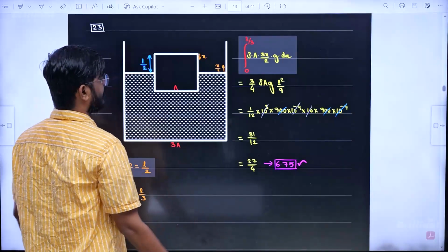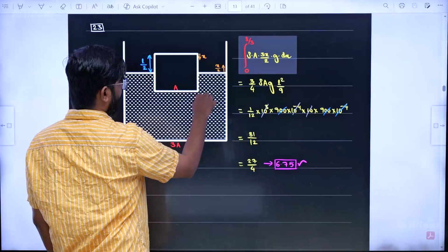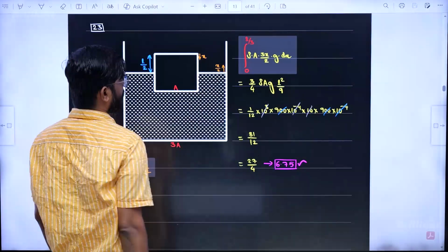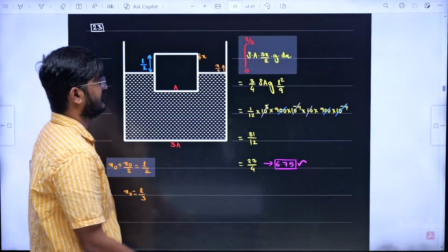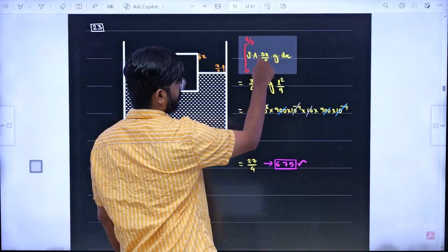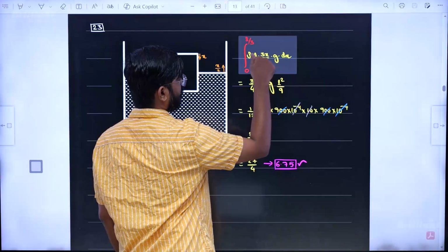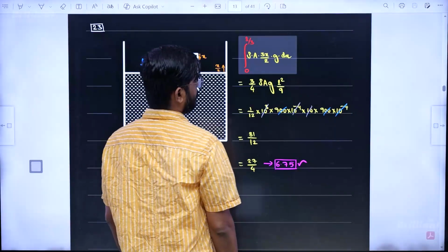Now in that case, extra buoyancy, extra volume submerged. Now this is going to go down by x and water level is going to go up by x by 2. So extra length submerged is going to be 3x by 2. So extra volume submerged is going to be this much. So you need to oppose that much extra buoyancy. So work done by you will be this much for a small distance.